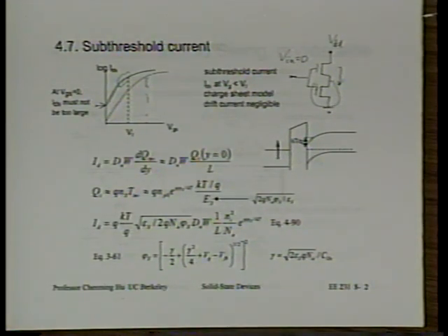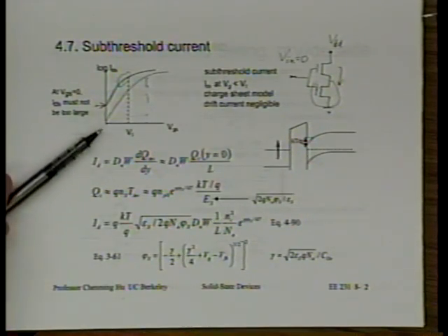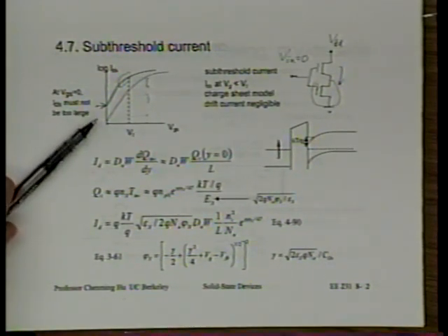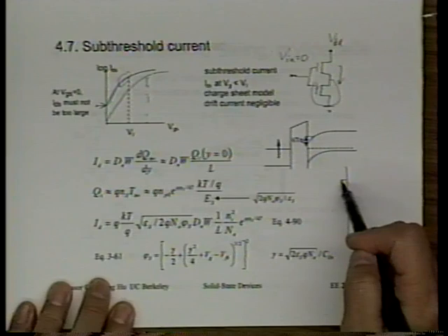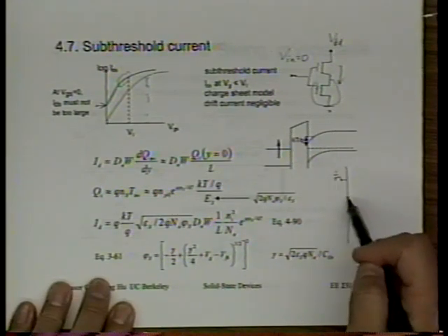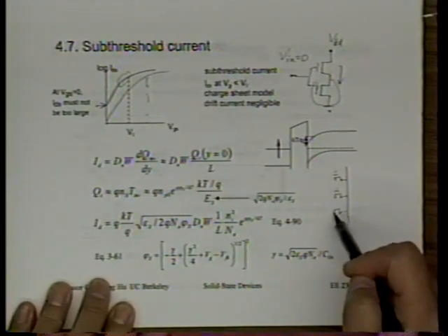Okay. So, just because there are several good questions about why we're concerned about this subthreshold current, let me give you another example where we're concerned about it. If you think about the way memory arrays are organized, whether it's static memory or SRAMs or non-volatile memories, you probably recall that it has to do with a bit line with many bits of memory connected to it, or many transistors connected to it, all right?